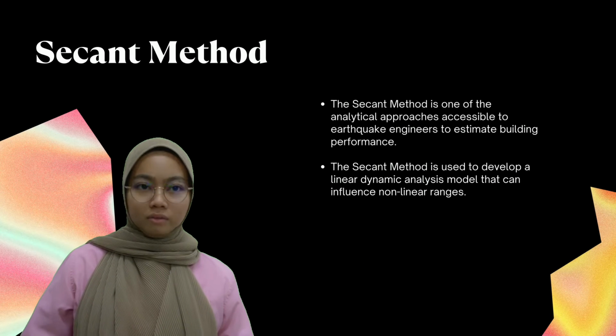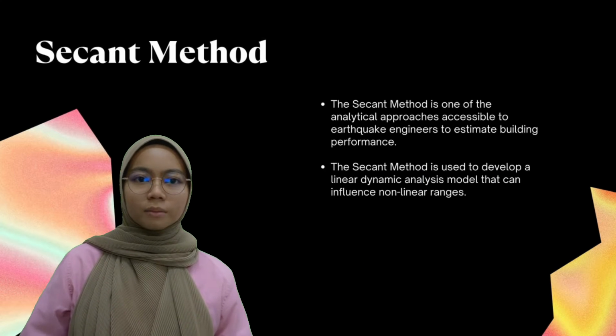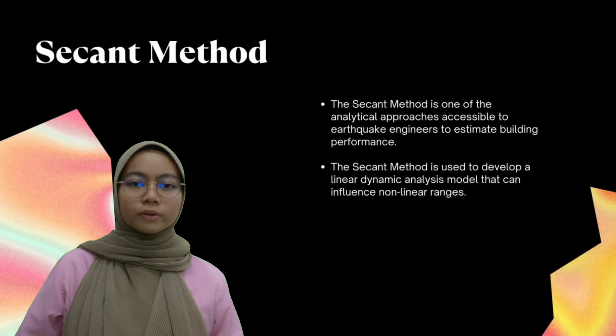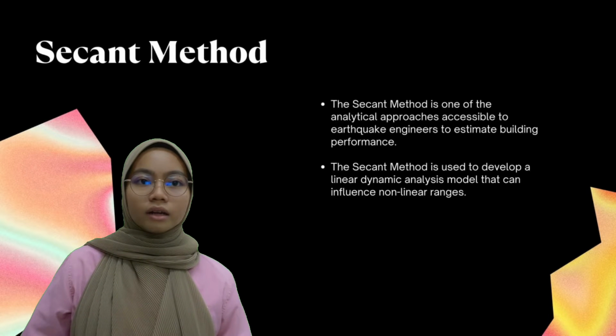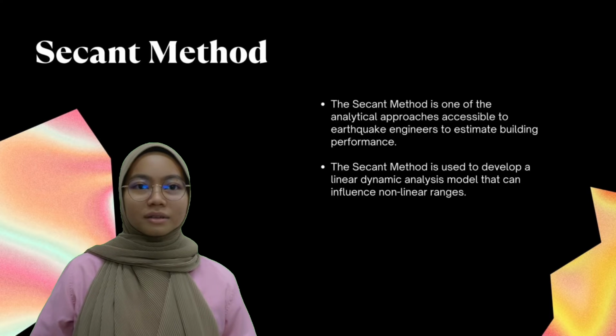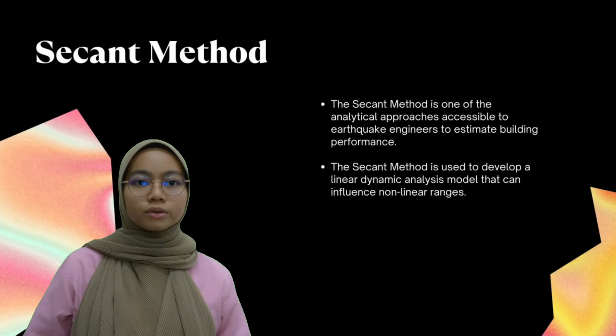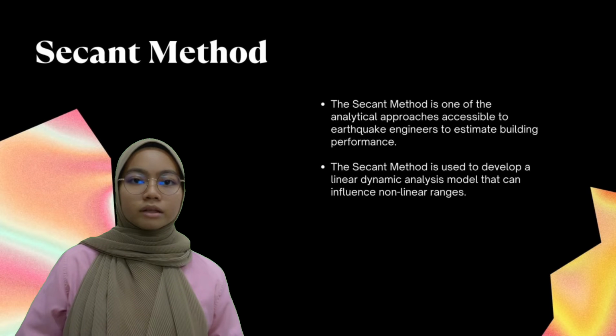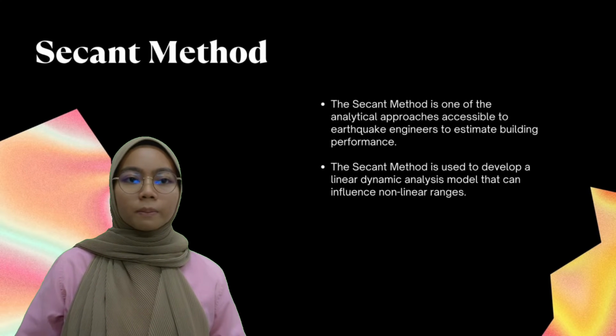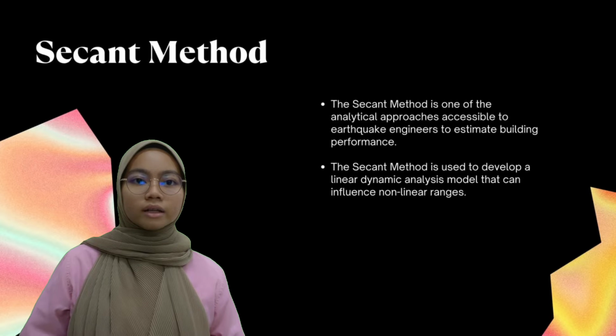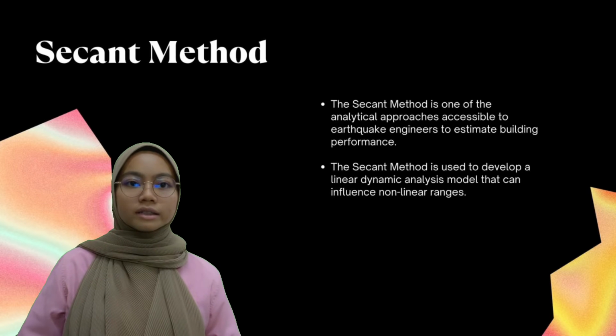And for earthquake engineers, the second method is one of the analytical procedures that are available for estimating earthquake performance of buildings. The second method is used to create a linear dynamic analysis model with the ability to capture the structure's behavior in non-linear ranges.